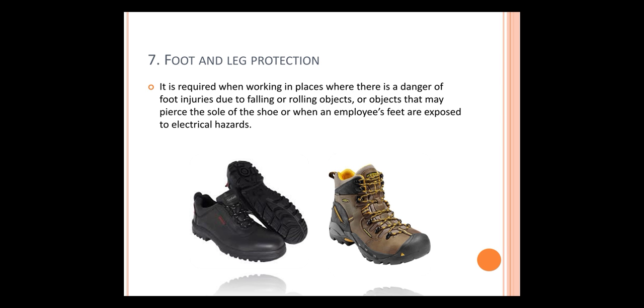And the one on the right side is the electrical hazard safety shoes. These are non-conductive and protect against open circuits of 600 volts or less under dry conditions. The insulating qualities may be compromised if the shoes are wet, the rubber sole is worn out, or metal particles are embedded in the sole or heel.